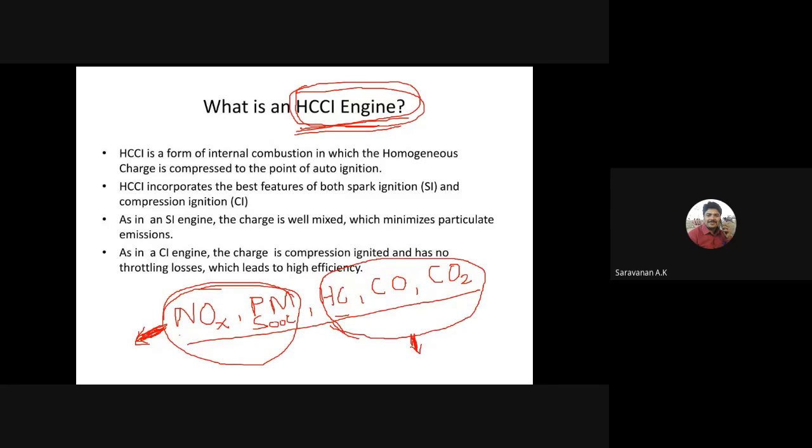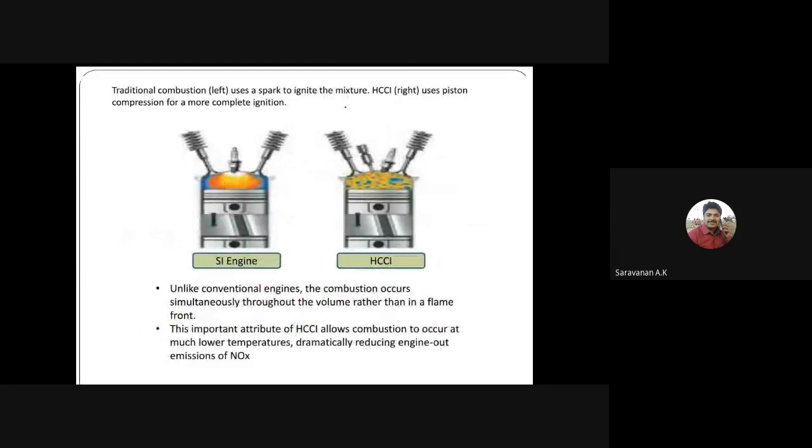HCCI engine, right? So what is HCCI combustion? That we can see. In HCCI mode of combustion, the fuel and the air are mixed prior to the start of the combustion, and the mixture is auto ignited. You may note this one, right?